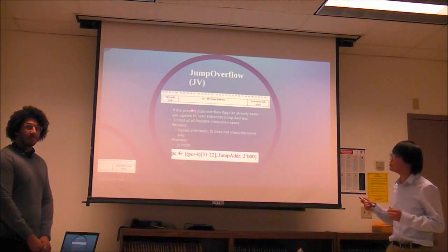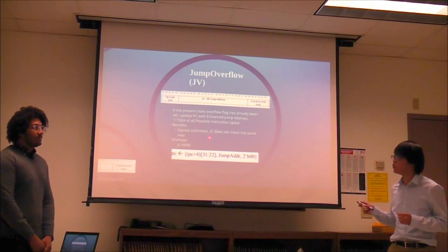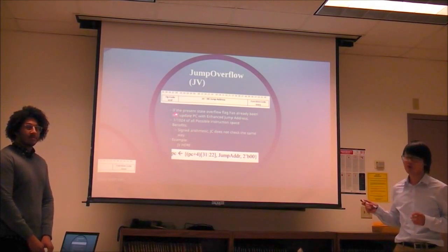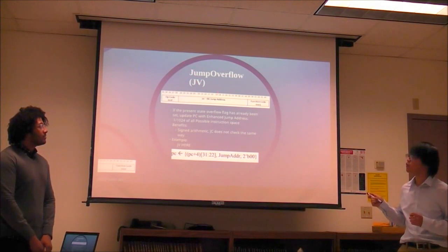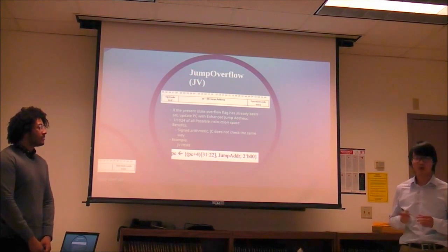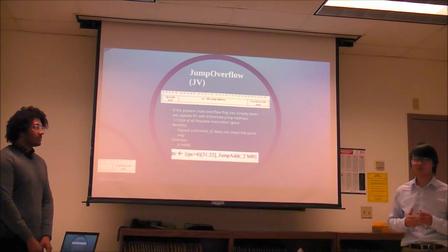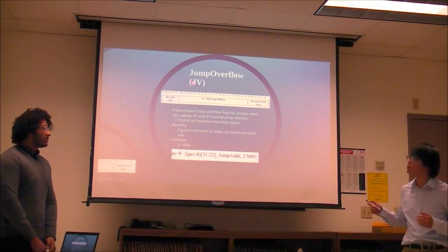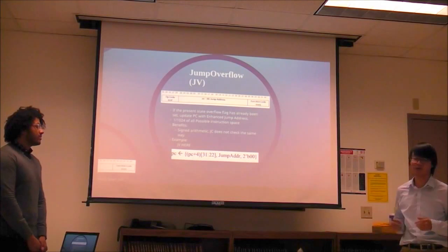If it was unsigned, then jump if carry will still jump, and jump if overflow will still jump. But since it is signed, the logic is different, so this one might jump while this one might not.